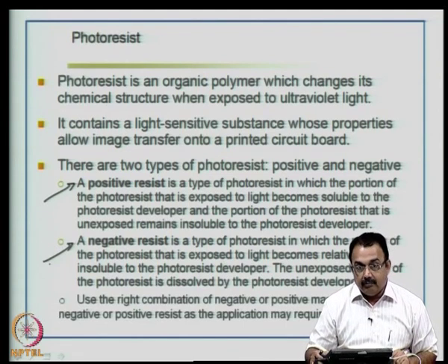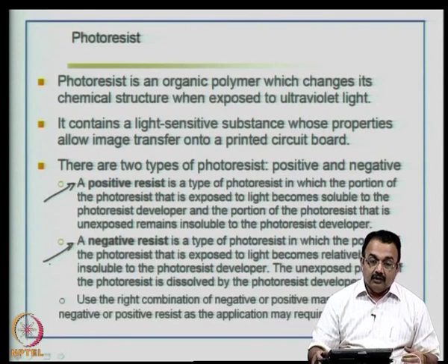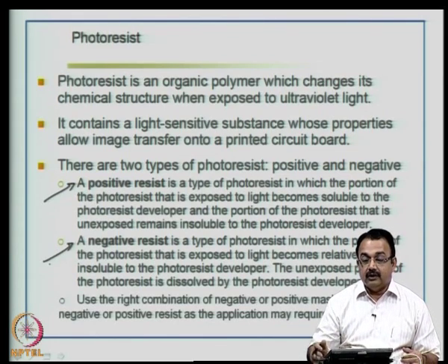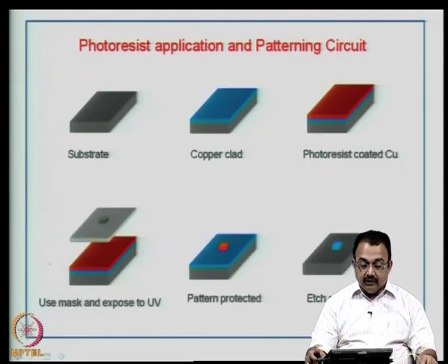Depending upon various structures, these are very important if you are going to build micro via structures and fine lines on boards. A negative photoresist and positive photoresist have different chemical properties when they are exposed to the UV light, resulting in a different solubility in the developer. So, use this very judiciously.